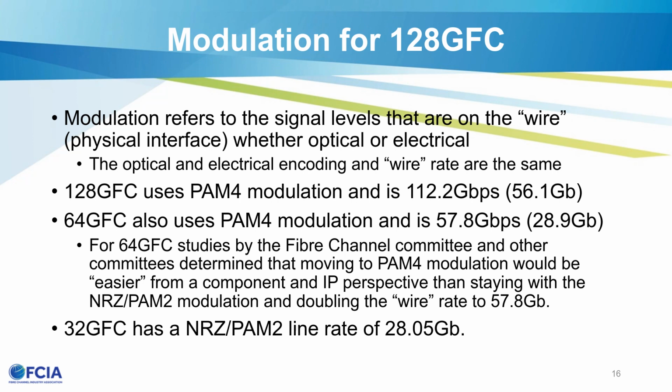So there was no way for us to go ahead and get that by any kind of transcoding or tricks with the data stream. So we had to increase the actual line rate to basically get the same overall doubling of throughput in megabytes per second, but we needed the additional line rate to compensate for the more complicated FEC to close the budget.